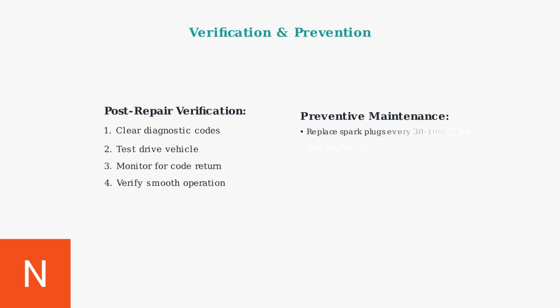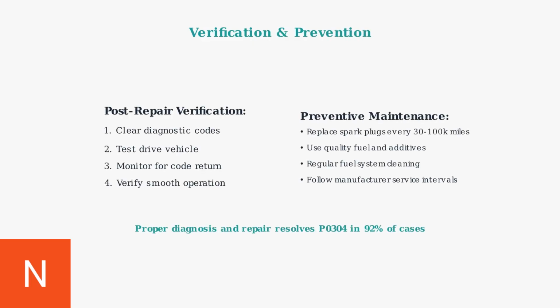Always use quality parts and follow proper procedures. After completing repairs, clear the diagnostic codes and take the vehicle for a test drive. Monitor for code recurrence and implement preventive maintenance like regular spark plug replacement and fuel system cleaning to prevent future P0304 codes.